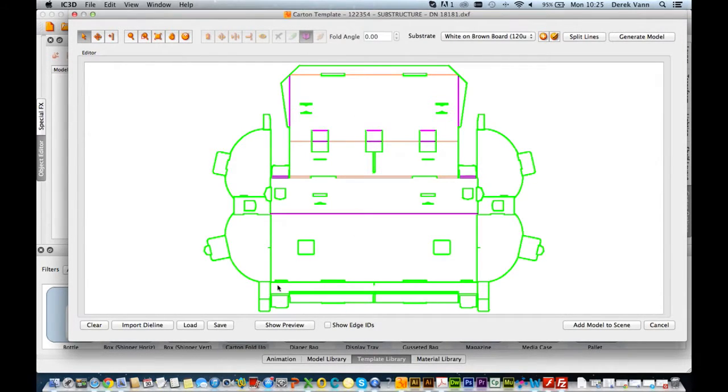The next set of lines can be set as collinear folds. However, as we Shift select the middle section, there is an unwanted cut component selection. This can be deselected by holding the Alt key and clicking on the unwanted component. The remaining lines can then be selected as normal and made into linked folds. Build up the remaining folds as individual folds.